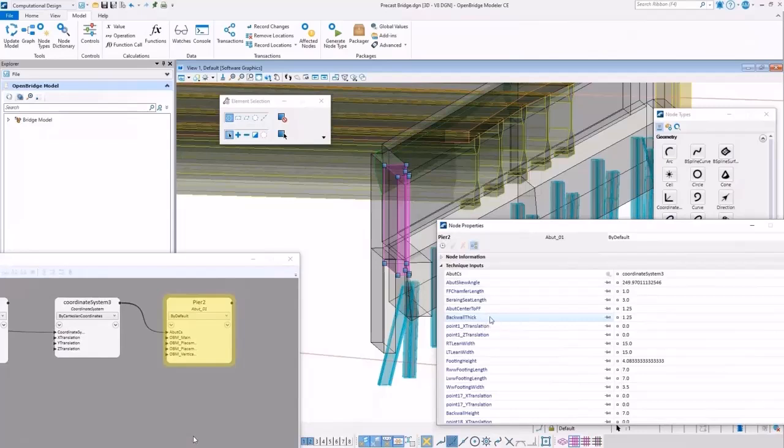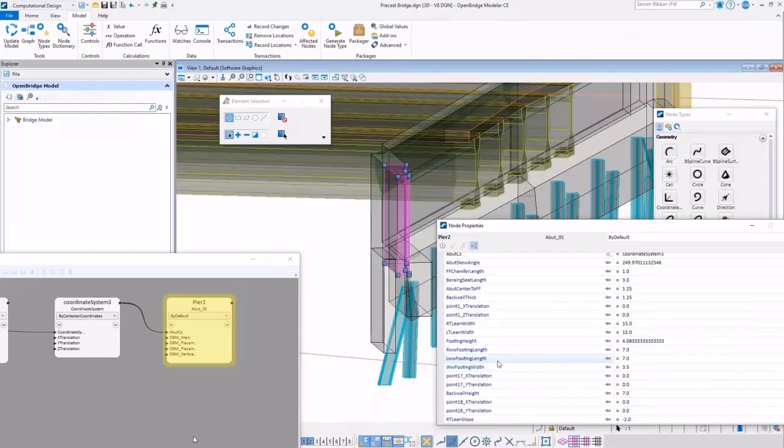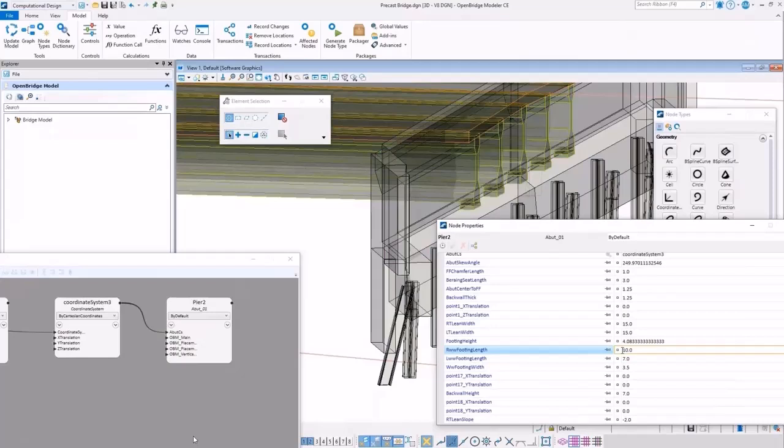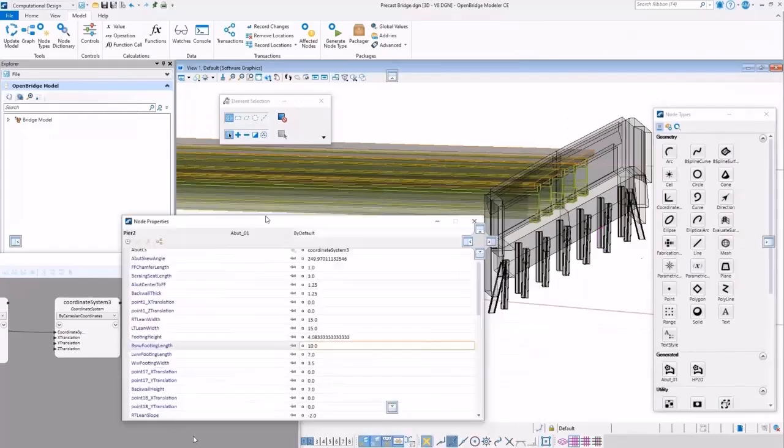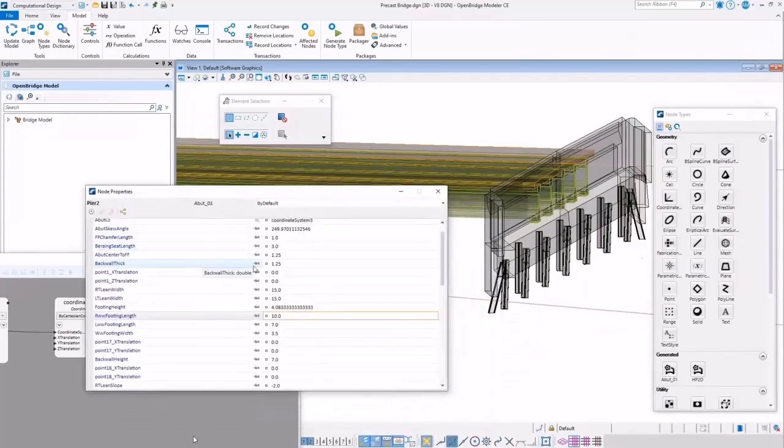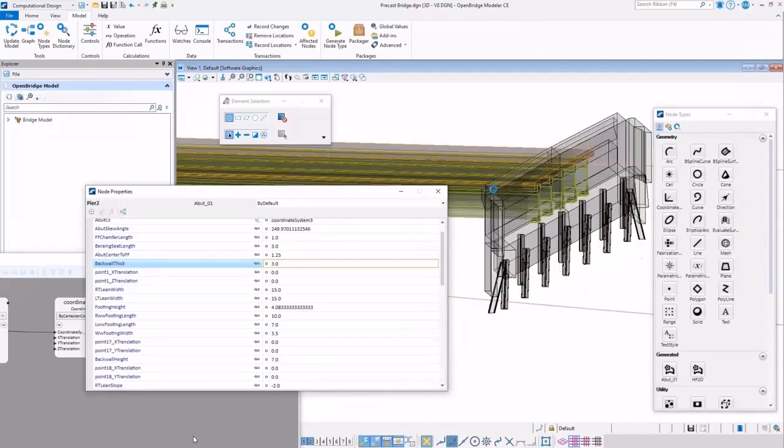So whatever the administrator or the creator of that GC node considered appropriate. And then for me, it's just a matter of, oh, the right footing of the wing wall. So I change the dimension that is given to me, press enter, and the element will just regenerate right in front of your eyes. There is no executable needed, it just does it, right? So maybe the number of piles is not set, but the batter angles are all zero. So again, if it's a variable, I can define any dimensions and it switches immediately, right?